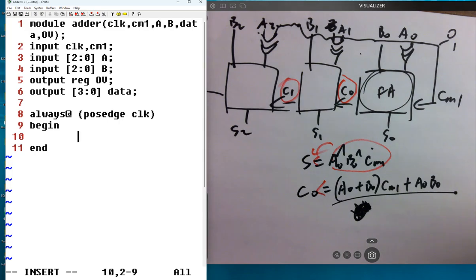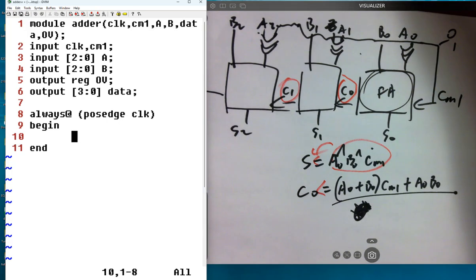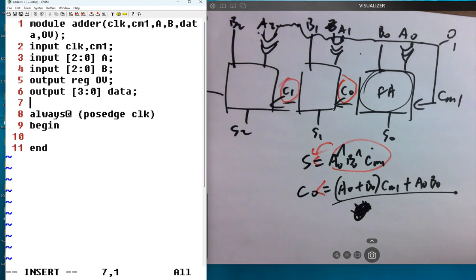It's just an adder. It's not supposed to do anything else. It's just adding or subtracting, right? Depending on the input. For the As, you have a very definitive answer because we already have the logic expression over there, right? So we can define what. As has 3 bits, right? So As will not be ports, and there will be a register type because we don't need an As to be ports, and because we need the data to be the final output.